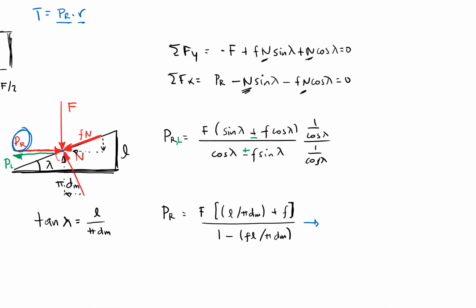So I was not really interested in PR, I'm interested in the torque. If I do that transformation here, I would get a T sub R. Again, R and L are going to be slightly different with the different signs. The radius that I would be using, this radius right here, would just be equal to dm over 2. So the mean radius where this point is located, this point where all the red forces are located, over 2, just to get the radius instead of the diameter.